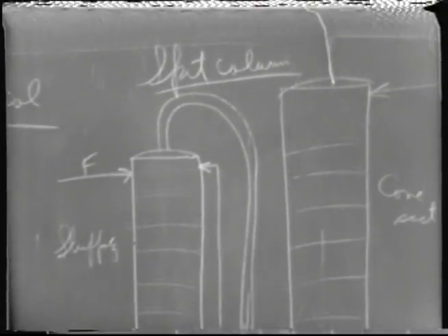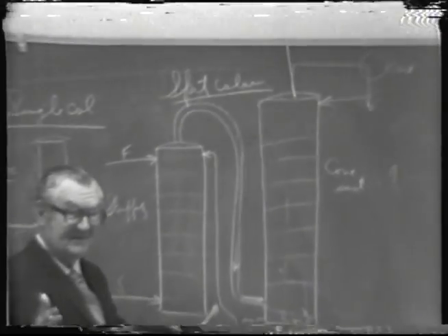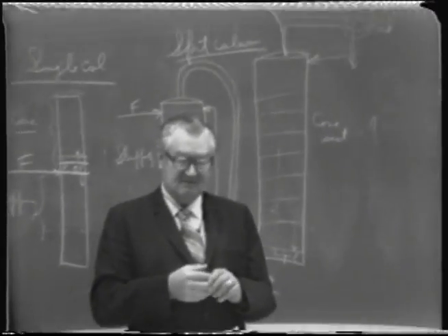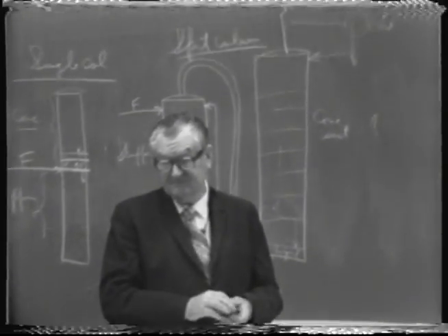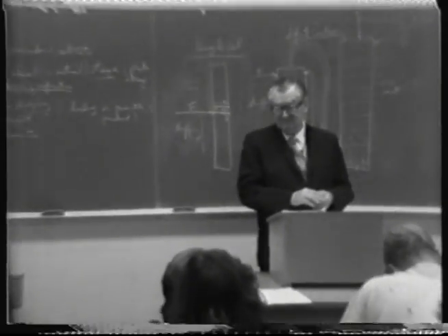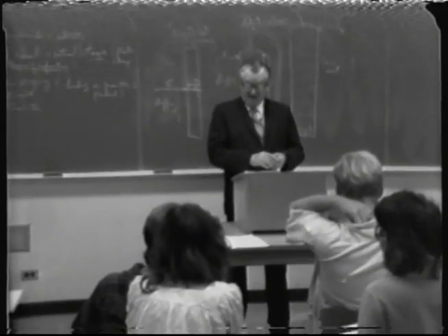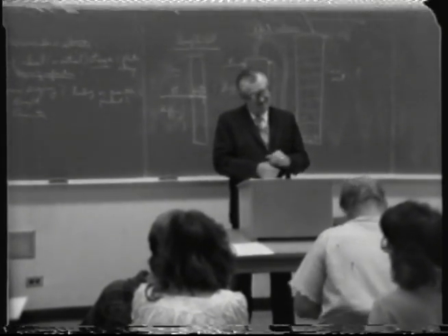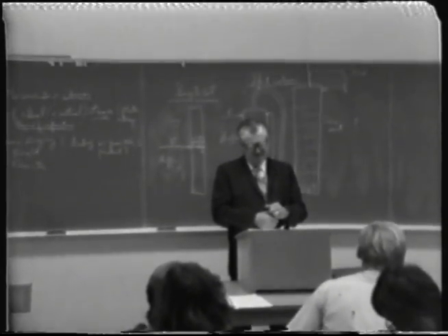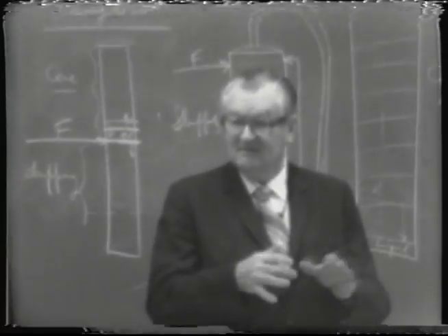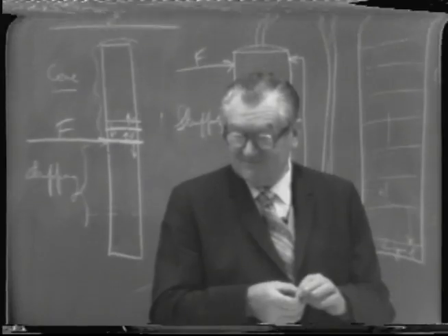But it's still about the most simple type of a continuous distilling unit in that there's only a stripping section and concentrating section. Well, why isn't the second part of the column heated? I mean, if you heat it, wouldn't it? Yeah. If you apply heat, there are types of units where you apply heat to the second column, but then you become truly a second additional column type arrangement.